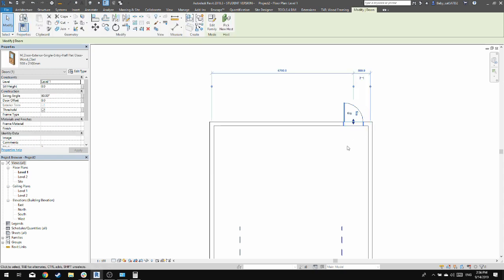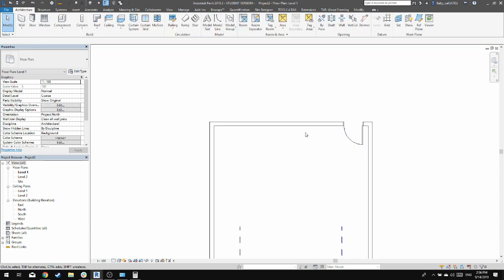And we can select this door model in order to fix the orientation of the door. We can click on the 2 arrows that are going in the direction perpendicular to the wall, flip which side the door opens onto, and then the arrows that are going parallel to the wall just switch which side the door opens to.